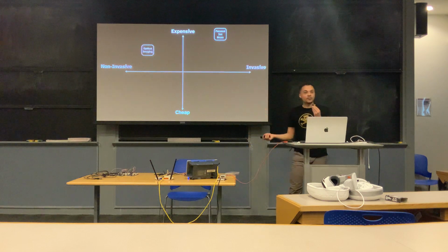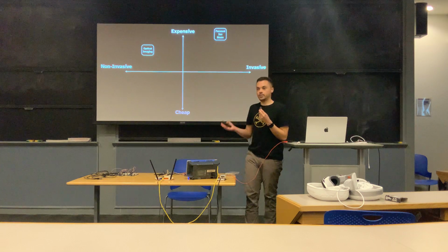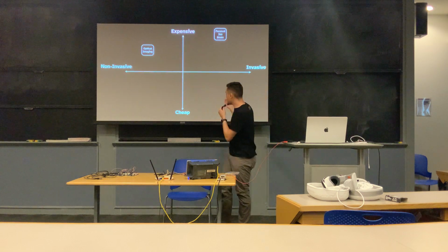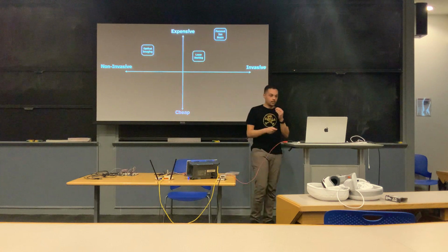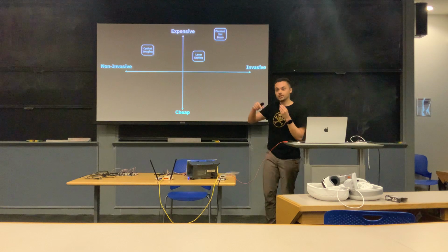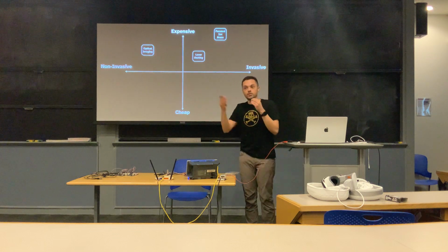We also have things like optical imaging. So this is less invasive. You're able to just take pictures of the device, but depending on how accurate your camera is and how much optical detail you want, this can get really expensive. There's also laser etching. So the idea with laser etching is you're going to actually etch into the chip with a laser to change different things. For example, like you might want to change a fuse, for example.